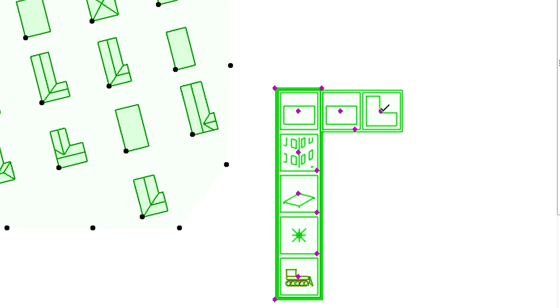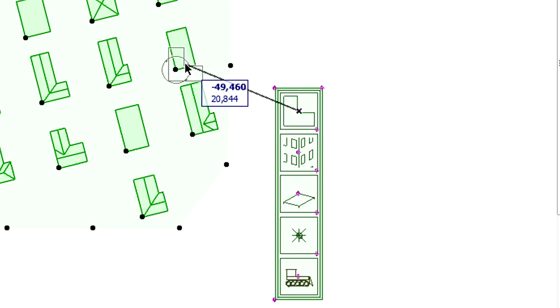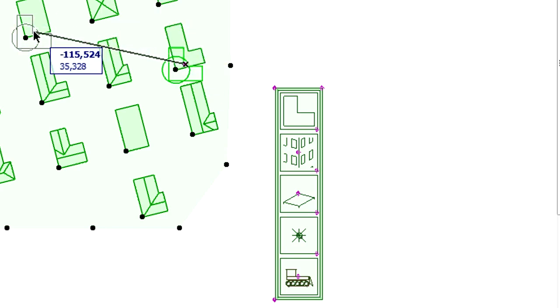We can select any of the building forms by clicking and then dragging its hotspot upwards. The new building form is now displayed at the top of the palette. We can drag and drop this building form on an existing random city building to replace it with the new form.